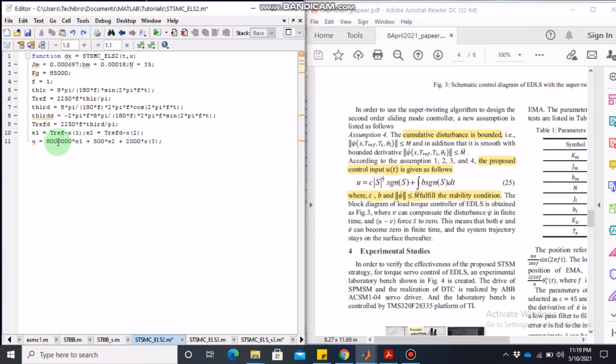which is the proportional gain. This is the proportional gain. I know this is a very large gain, but small gains did not work, so I just randomly put in some numbers that work. I have not worked extensively on designing this PID control. You can go ahead and do some tuning of this control and get better results than I present in this video, and then that will maybe lead you to some sort of research contribution as well. That's my goal, to enable you to do research on your own.